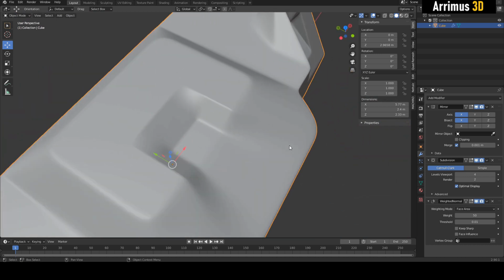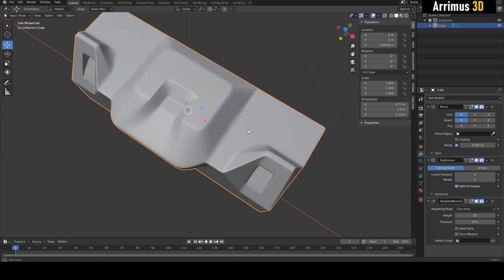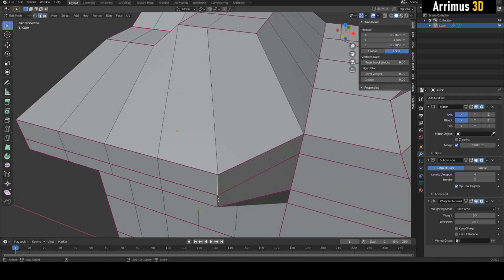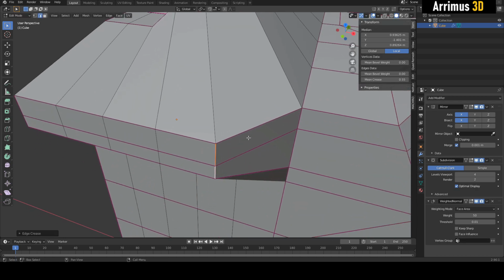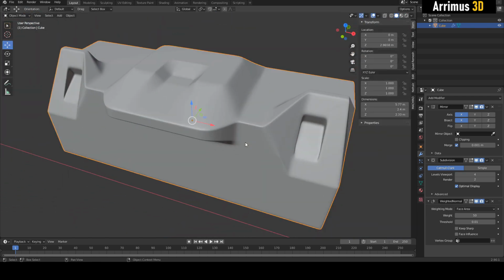We did learn one new tool actually, Shift E, to just quickly crease things on the fly. That can be very useful as well. So for example, I can select this, hold Shift to add right here. Shift E, tab, it's now sharper. Shift E, move to the left. It's now smoother.